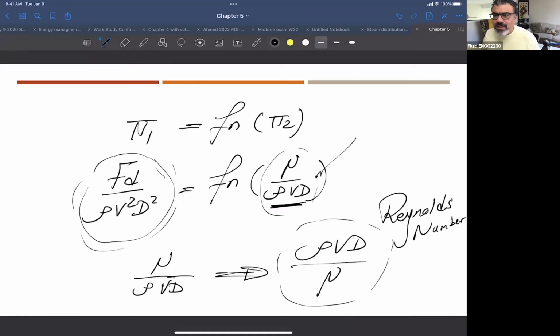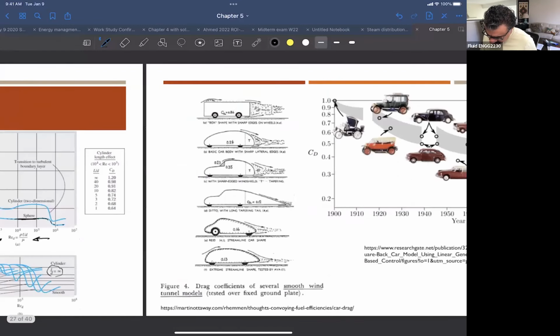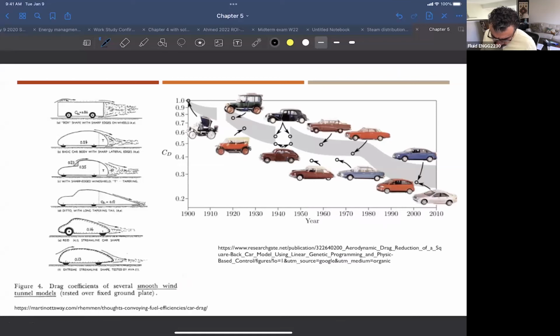Okay, can you find out what is a non-dimensional group? You have unit length L, right? Of course, you can just say, oh, L is going to be divided by D, right? Because D is one of the repeated variables, right? A will be 0 and B will be 0. Only C will be -1, so it's going to be L over D. So from your practice, you can just look at the parameters. You can actually combine them, and you know it is going to be dimensionless, right? So these are very important conclusions about this.